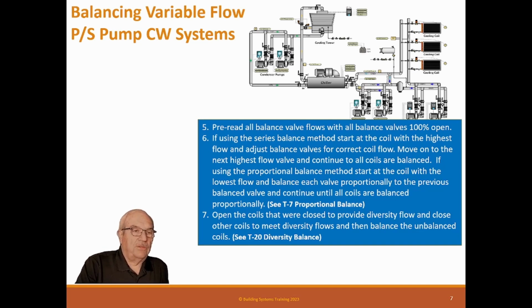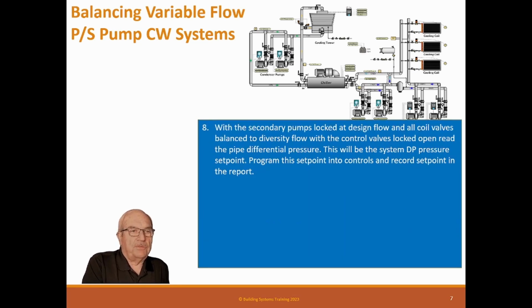And then we also have a session, T-20, on diversity balance, both for air and water, and it'll explain those to you. With the secondary pumps, okay, now this is really kind of important. A lot of guys balance systems by leaving the control system in charge of the system pressure, and you should not do that. You should just ignore the system pressure, right? Make sure that's not operating.